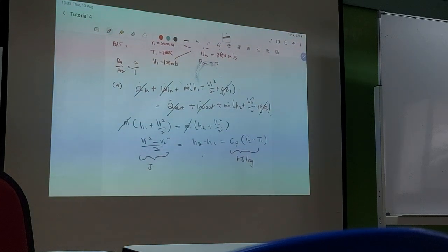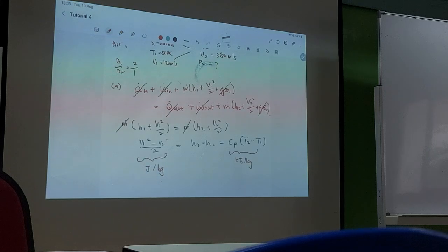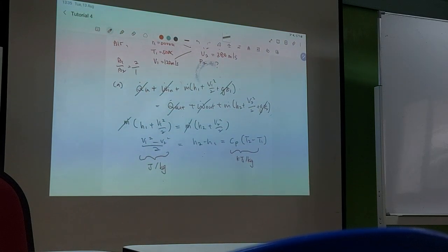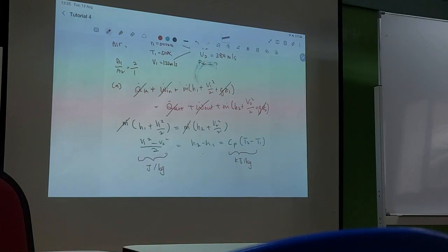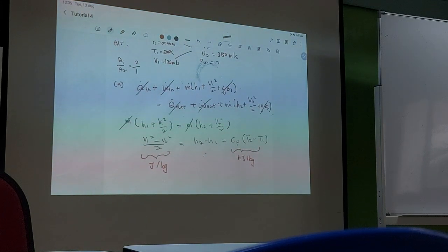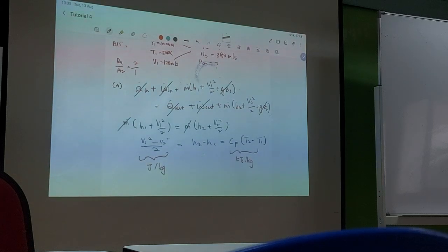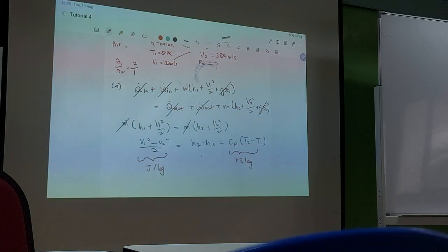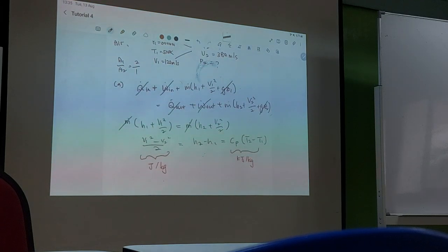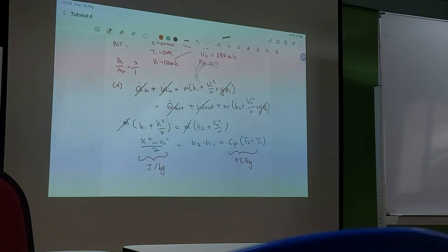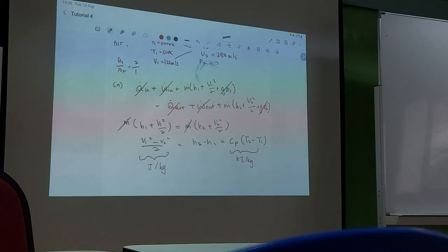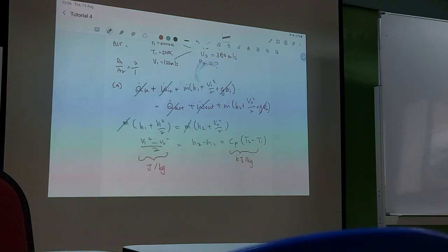This will give you joule per kg. So be careful about the 1000 here. This is one thing that you must be careful of, or else your value will be very ridiculous. One thing for you to remember: kinetic energy usually doesn't have a very significant effect on the overall energy change. So if you notice that it changes your value by too much, then something is wrong. Potential energy, then maybe yes, you might have a lot of effect, but velocity, kinetic energy, no, not much.